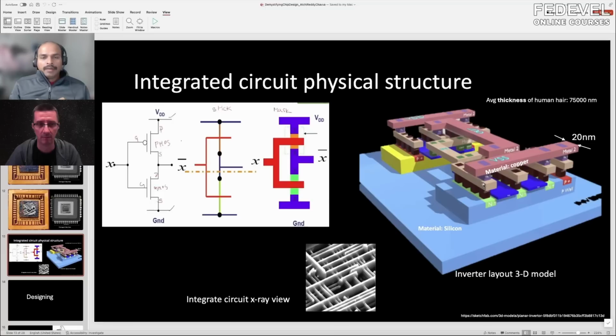The reason is that at the lowest level are the active devices, the transistors, and we're trying to squeeze more transistors per square inch. We can do that by shrinking the size of the transistor. So every new process node, the transistor size is shrinking, so we need thin structures to establish the contacts. On the lower level we do have these narrow structures.